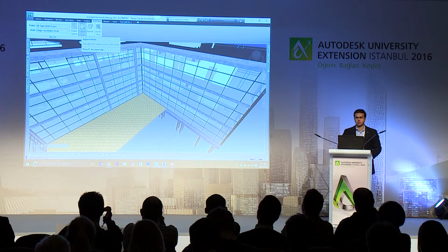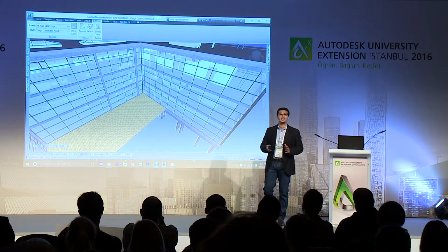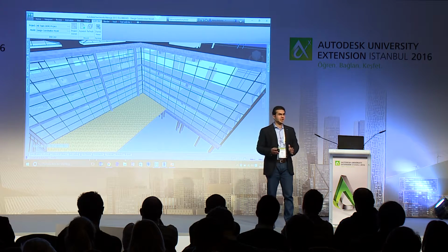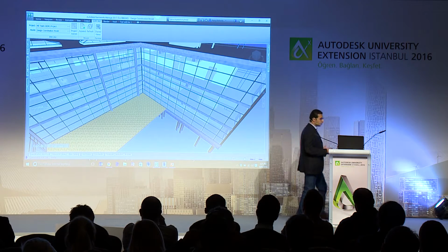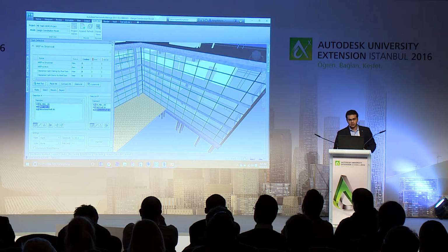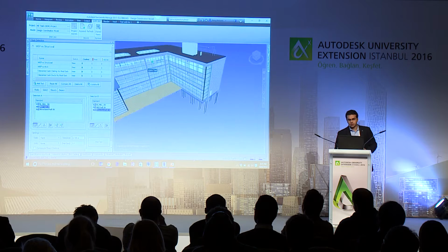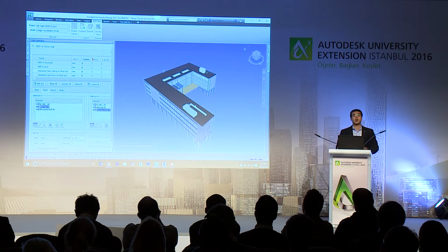That was the clash detection. In the background, Autodesk Navisworks and BIM 360 Glue are sharing the same core technology for finding clashes. But what extra can be brought by using Navisworks? Navisworks clash detection is a kind of advanced clash detection engine. In BIM 360 Glue, you may have noticed something: you can only perform what we call hard clashes.